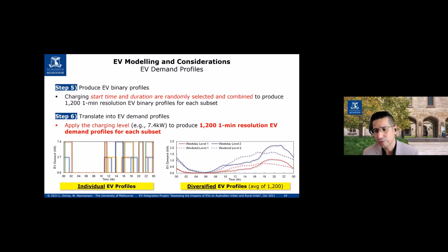And also the fact that a level 1 charger normally has a demand of around 3.7 kilowatts. The moment that we have hundreds of electric vehicles charging at different times, on average, that peak demand for level 1 charging is around 1 kilowatt something. So a third. And for level 2 it is 2 kilowatts something, 2.2.